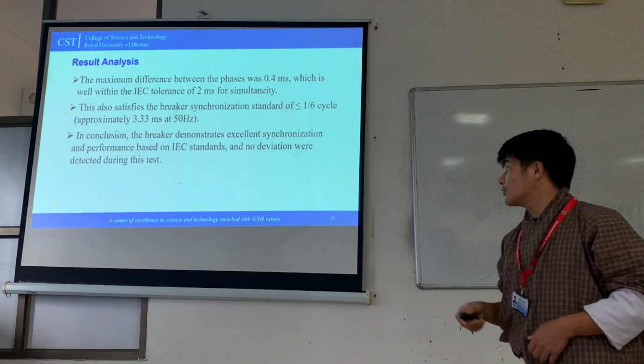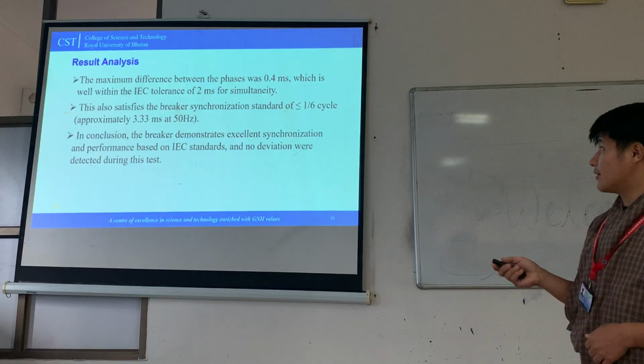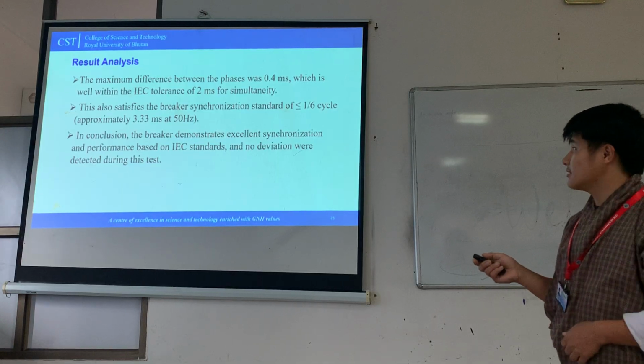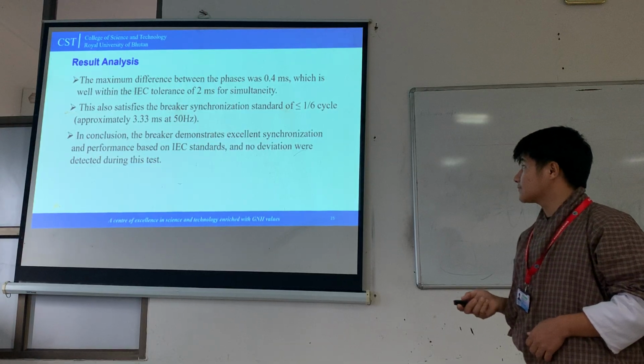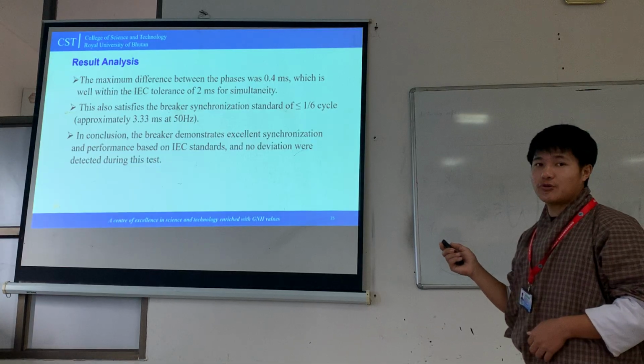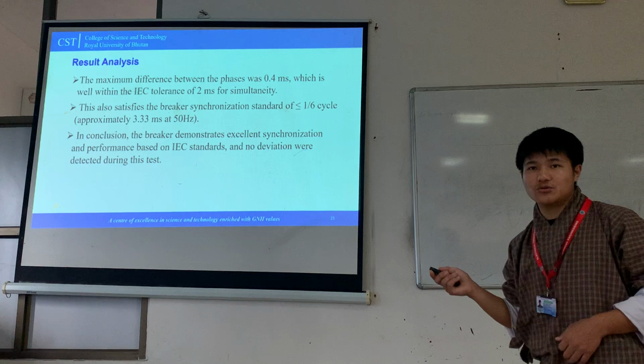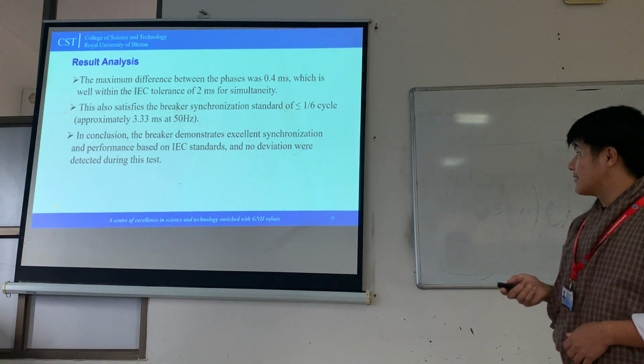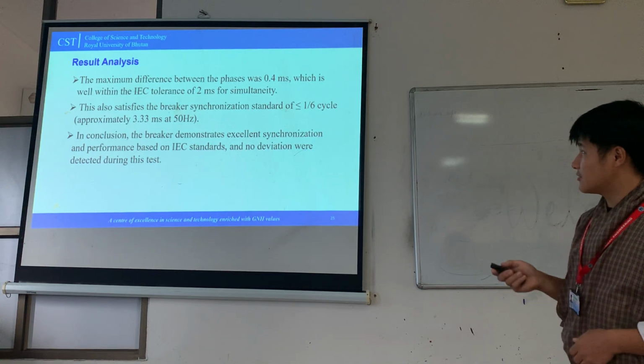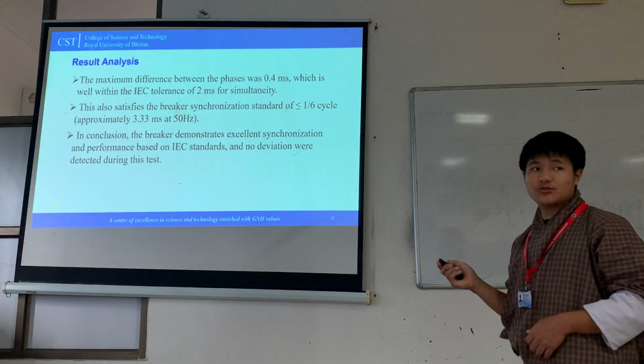So from the above discussion, we can say that the maximum difference between phases was 0.4 milliseconds, which was well within the IEC tolerance, which is 2 milliseconds. So we can say that the breaker demonstrates excellent synchronization performance.